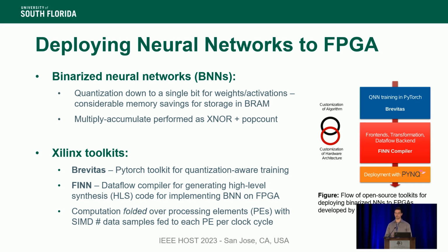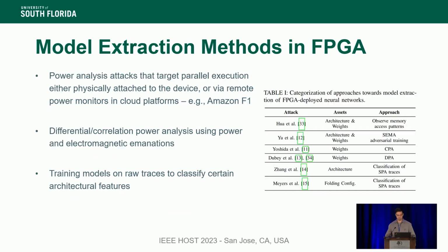And essentially it involves folding the computation of these BNNs over a number of processing elements, or PEs, with a number of SIMD data samples fed to each PE on every clock cycle for computation.